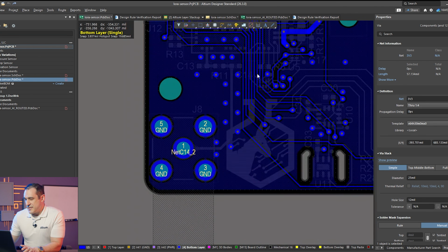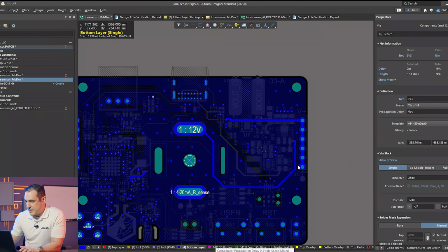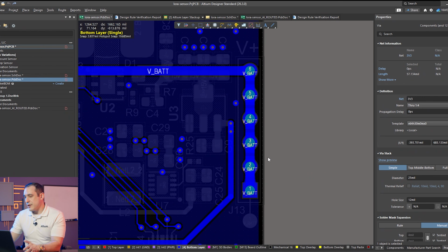Some of the things I did notice in this design, I noticed that there were 6-pin headers that were used for the input power to connect to what looks like a battery. Here, if you do have these 6-pin headers, you do get really high current handling capability, but of course there could be some more compact 2-pin connectors that would allow you to have the same level of current handling without having to have these input and output side headers on each edge of the board. That's just a personal choice or more of an engineering choice. Also, it's kind of a mechanical or form factor choice, so it's probably what I would do if this were my design, but I don't think it really impacts the functionality.